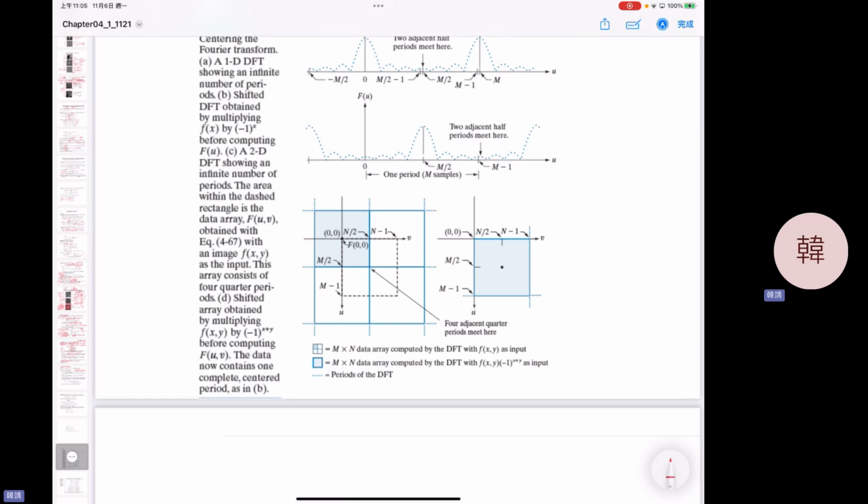If you apply this in your original image, can you expect what the result will be? Okay, it's a low-pass filter, right? Which means I'm going to smear the image, smooth the image. And the original one will become like this. Immediately, the image will become smooth, smeared. Okay, how about the high pass? High pass is for the edge information. So the edges are clear, but the low frequency component disappears.